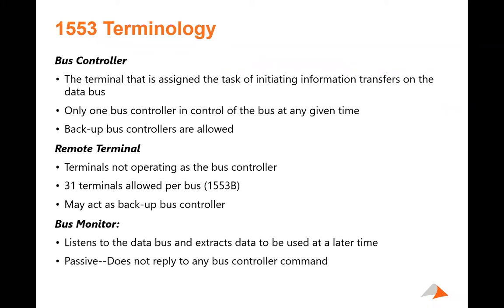But whenever you hear, in the strict sense of the word, a 1553 terminal, or the bus controller terminal, the remote terminal, in the strict sense of the word, it's just the 1553 part of the unit, but it's just become now that everybody uses whatever the LRU is that's doing the bus controller. They just call that the bus controller.